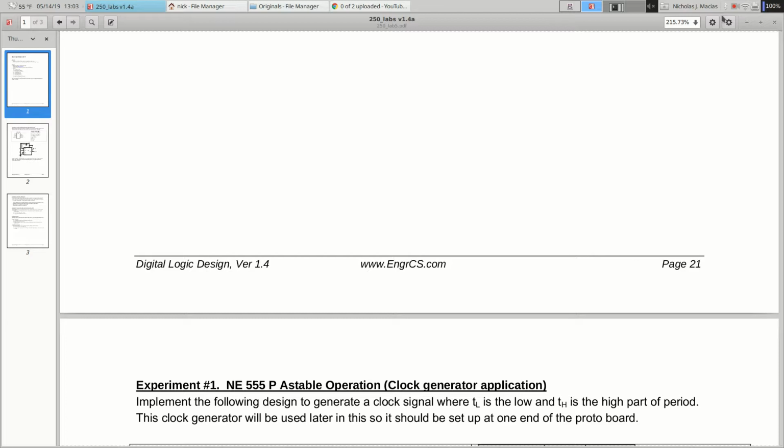You said programmable, does that mean it could be done from the computer directly to hardware? Yeah, you can control what gets connected and what doesn't. You run some software and put in a truth table or equations, then connect a programmable device, usually through a USB port, put the programmable device in a socket, run the program, and it'll configure it to implement some behavior.